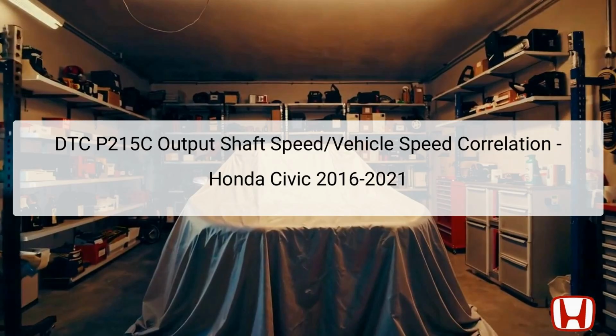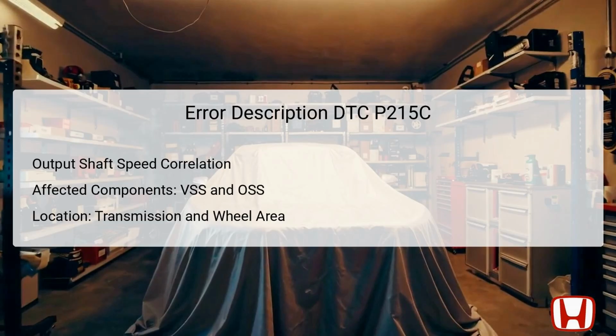When the output shaft speed doesn't align with the vehicle speed, it can trigger this diagnostic trouble code, DTC. It's crucial to accurately diagnose this code, as it may lead to complications like improper transmission shifting and decreased fuel efficiency. This guide will cover the detailed troubleshooting steps for addressing DTC P215C, specifically for Honda Civic models from 2016 to 2021. DTC P215C indicates a discrepancy between the output shaft speed, OSS, and vehicle speed sensor, VSS, results.